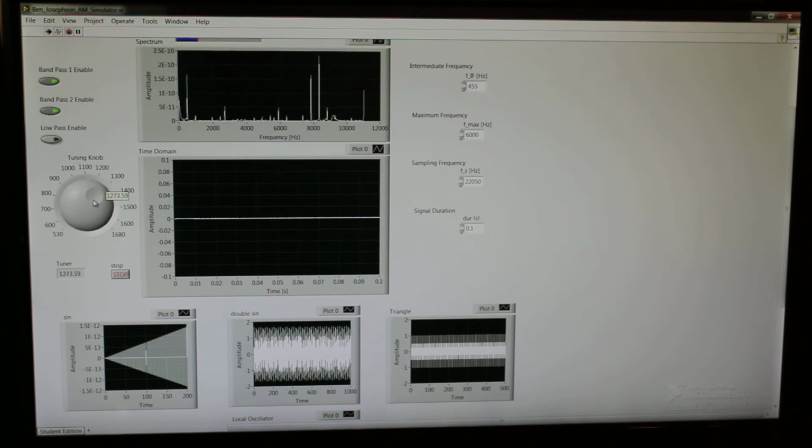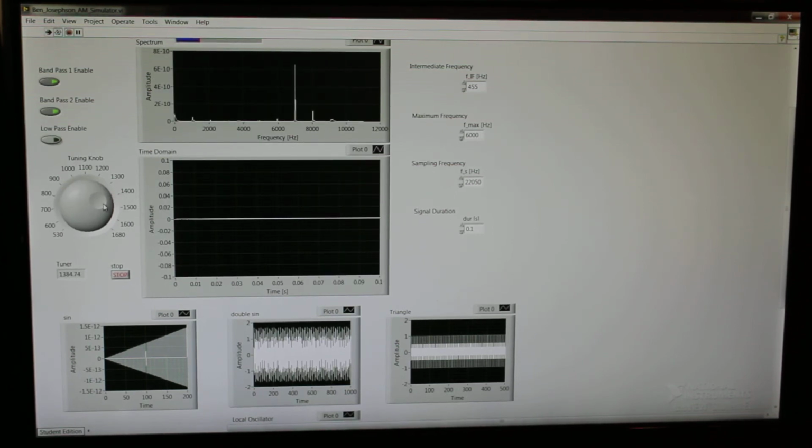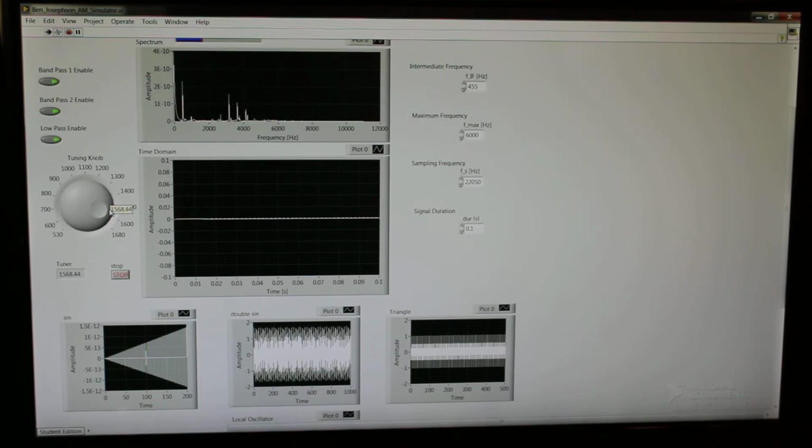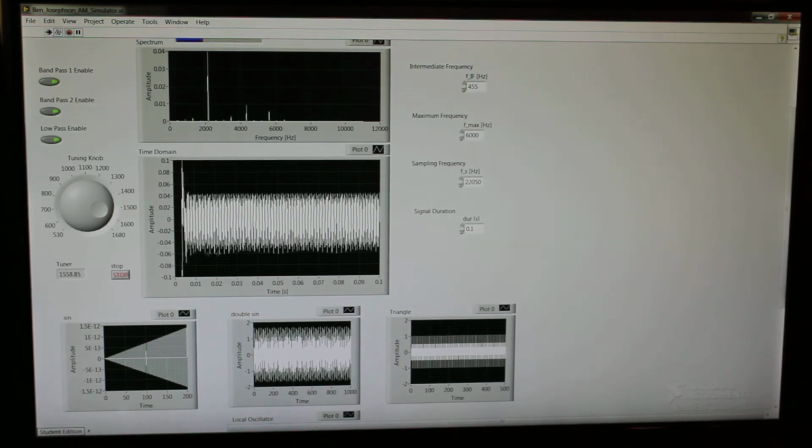Here, we've still got some noise on the high frequency end, so we have some spikes that are outside the range we're looking for, but if we enable our low pass filter, we're able to clean up that signal, and now we can start to hone in on those specific frequencies that carry the information that we're looking for. And in this case, we can tune back in on, looks like we've focused in on a triangle frequency here.